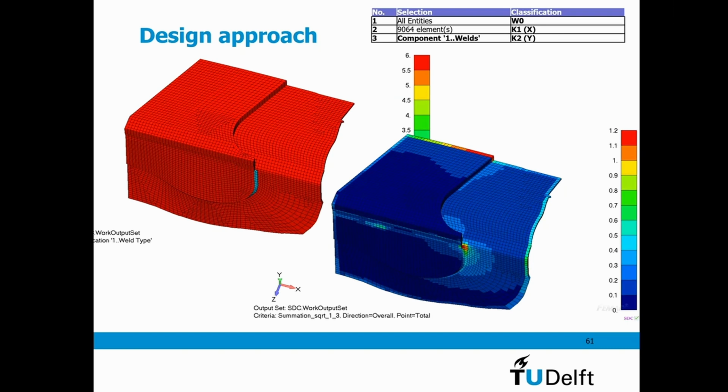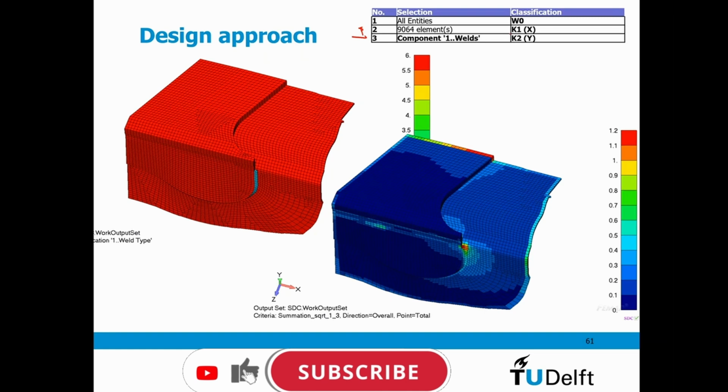don't make a difference between volumes and plates, and in volumes also the stress concentration of the design itself is taken into account. So I just transfer that into a better quality, a K2 for all my welds for stresses perpendicular to the line, and K1, because the stress concentration, like in a detail here, is then already included in your model.